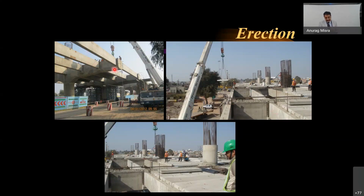I was telling you that once these are done, then you have to bring the precast beams. And because providing the restrainers would have created a problem, we left insert plates here, and after the beams were placed and the casting was done, the restrainers were provided in steel. So the insert plate was there, and the brackets were created here later on to stop it in case of earthquake and so on. Now you can see that after placing the beams, you put the precast slab units,